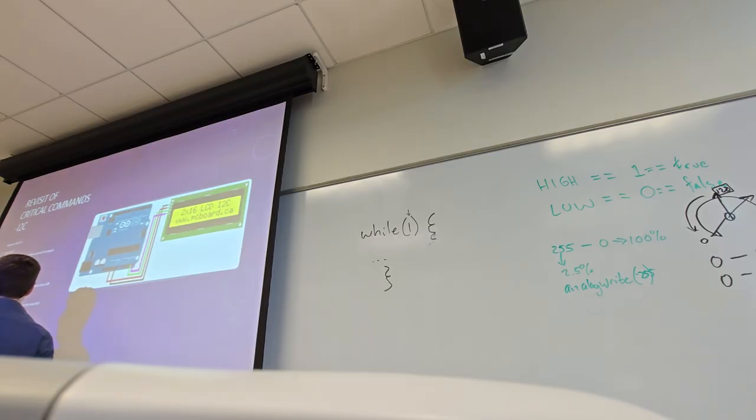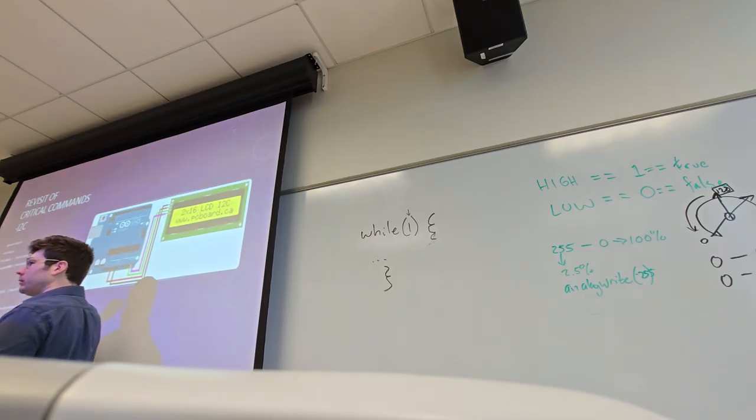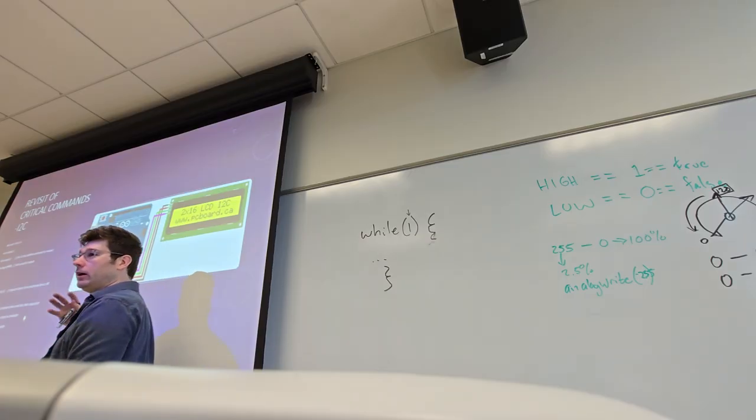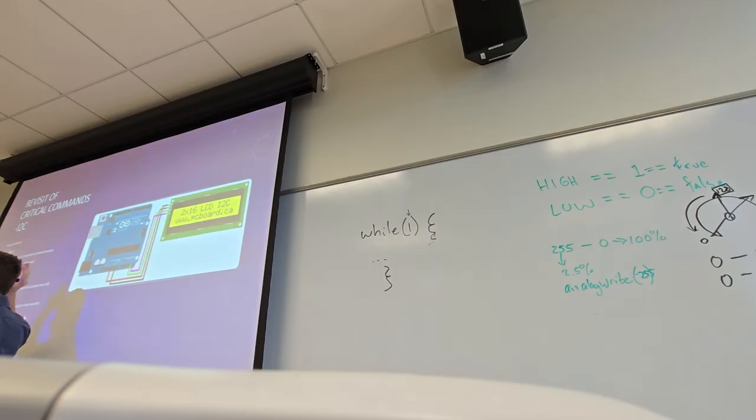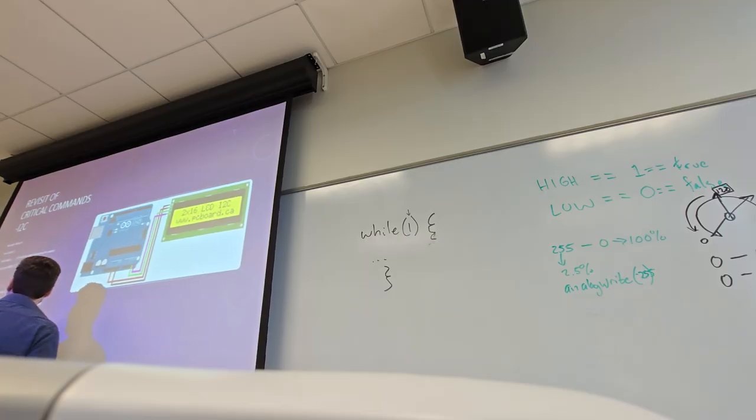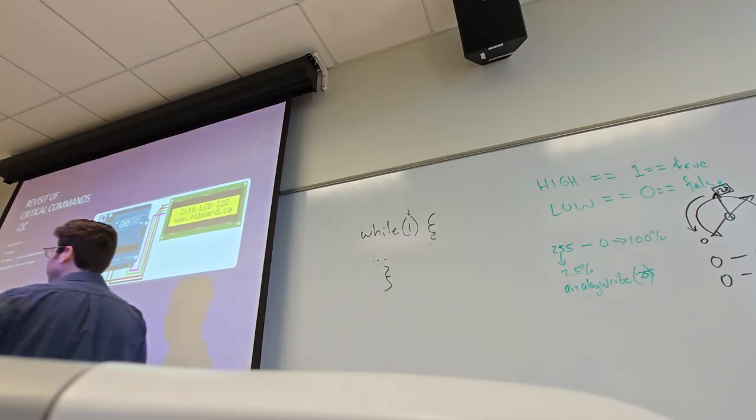Okay, because we had that little subsection of our brain that was just devoted to I2C. It can see when we get messages. A little flag comes up that says, hey, we have data ready and waiting. Our computer doesn't have to spend time fetching that data. We can just see, hey, there's 8 bytes waiting for you, whatever. There we go, cool, read in those 8 bytes. And then we were already expecting those, so we get our information back in the form of whatever.